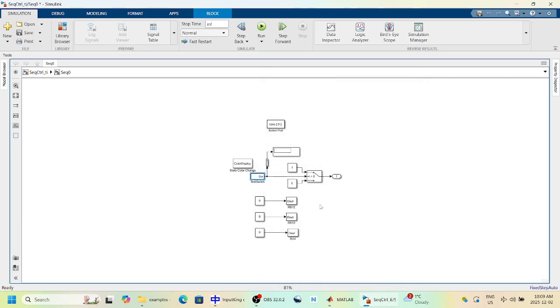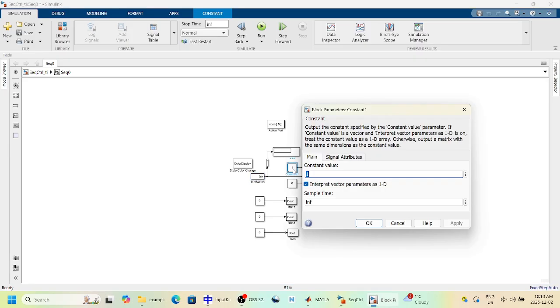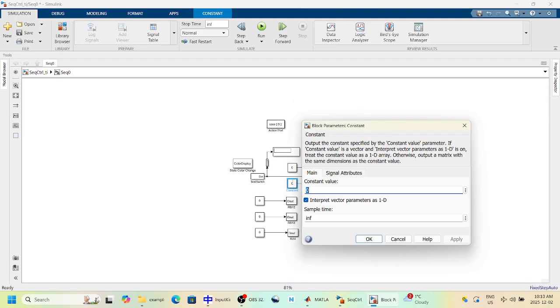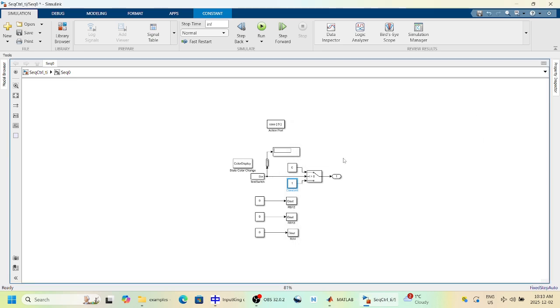From the schematic, we know the input is 0 when the button is pressed, so in the switch block, set the top input to 0 and the bottom to 1. This keeps the system in state 0 when the button is not pressed, and moves to state 1 when it is. Now rename the D-out blocks.